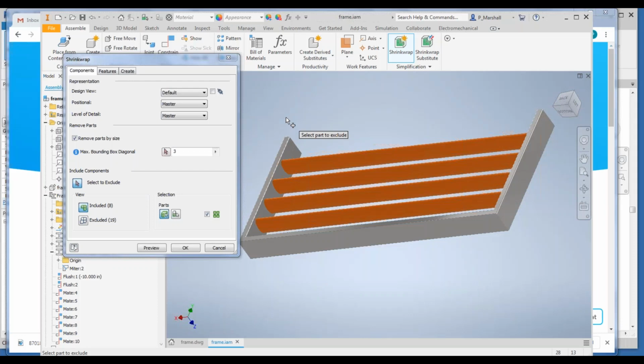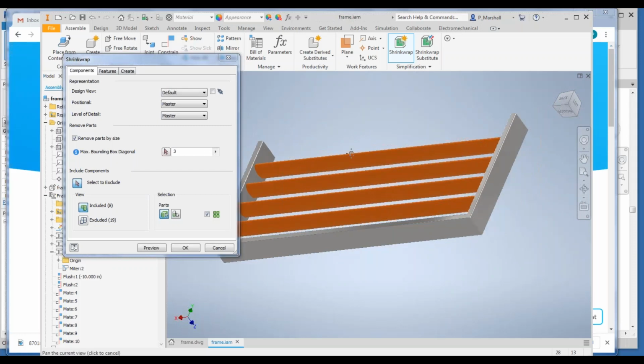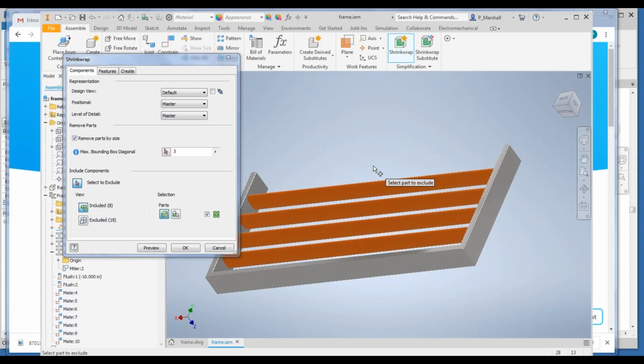One more thing we should do is locate the placement or origin point. The origin point for the Inventor design, when you're doing mechanical design, could be one thing, but the placement point in the Revit model may be someplace else. So in this case, what makes sense to the architect would have a placement point on the face of the building at the center of this sunscreen.